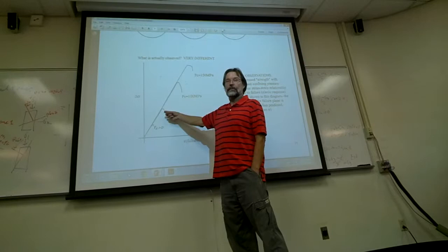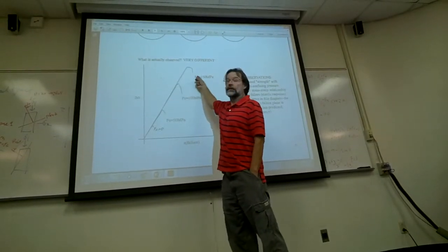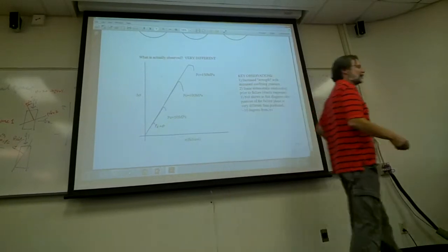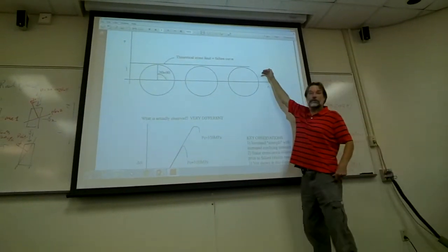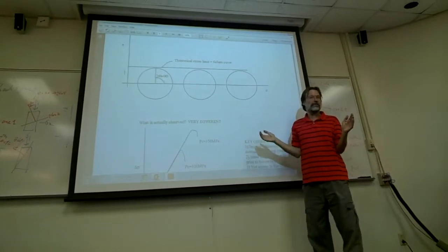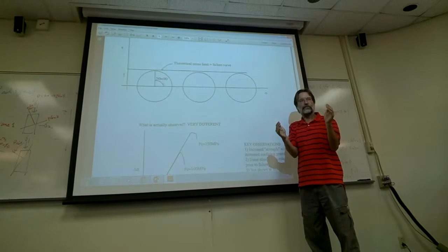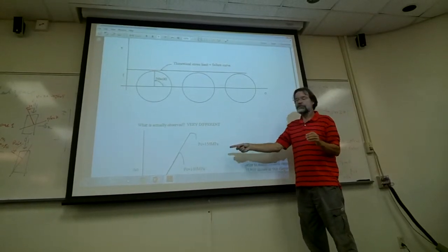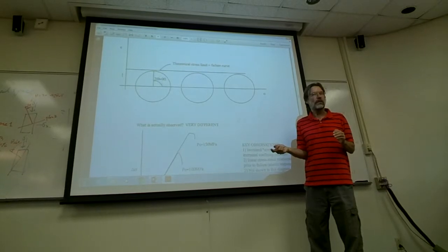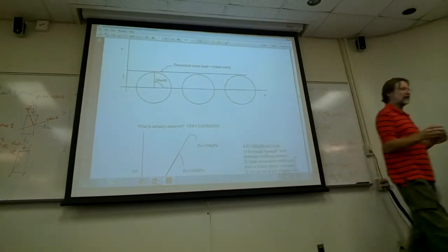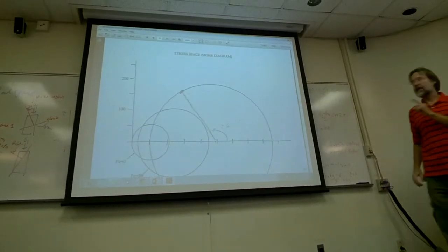At greater confining pressure, the strength increases, and then it increases and increases, which does not match this relationship, where this is a threshold value, right? Because the diameter of the Mohr circle is the difference between the end load and the confining load. But these experiments show that instead the material increases in strength with increasing confining load. If you were to plot that on Mohr circles, it would look like that.